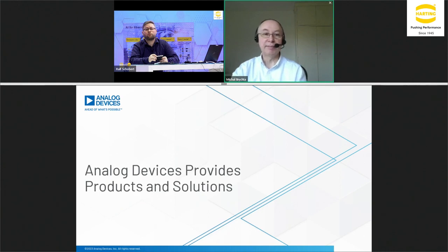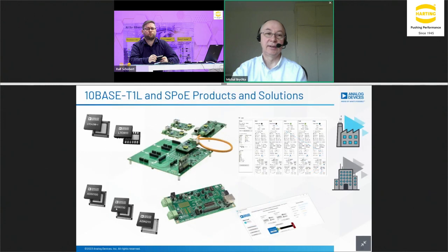So that leads me to the conclusion. At Analog Devices, we provide products and solutions for single pair Ethernet, and those solutions include 10BASE-T1L. We have a PHY, we have a MAC-PHY with a small level of integration, we have a 2-port switch for single pair Ethernet, and also, as was the main topic of the presentation today, we have the PSE and PD controllers for plug and play single pair power over Ethernet.